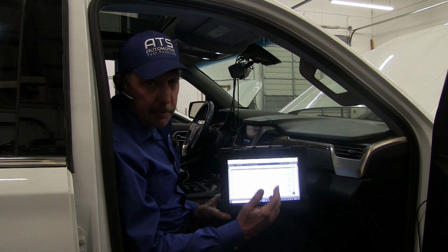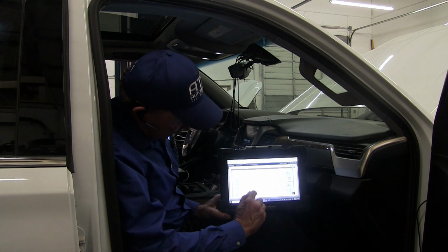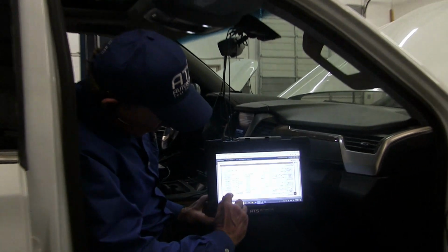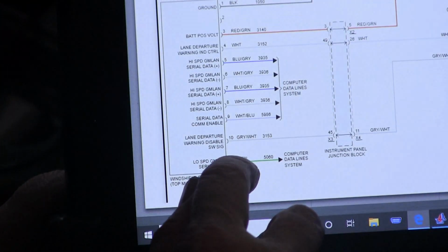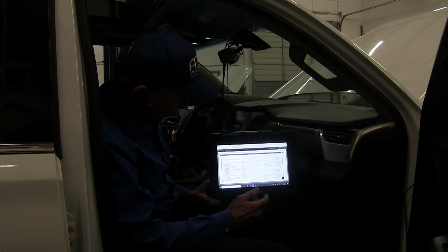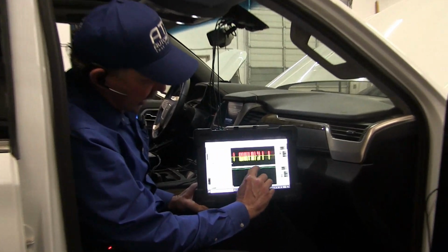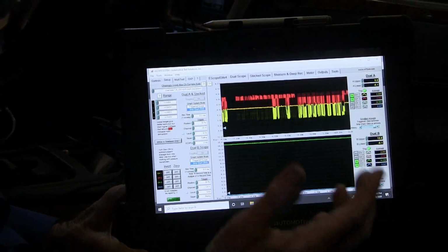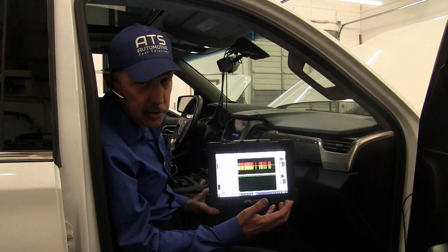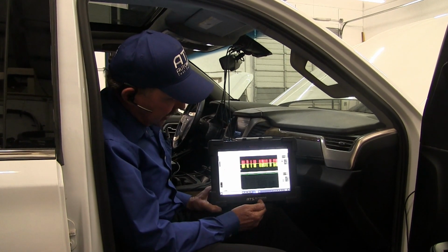Okay, so we've back probed and we're into these new circuits. The new circuits we're in are this LAN line and this serial enable line. So those are two that we need to see. Now we're going to come over to the scope and we can see that I have the high line that's going to enable the data stream, that goes high when it comes up.